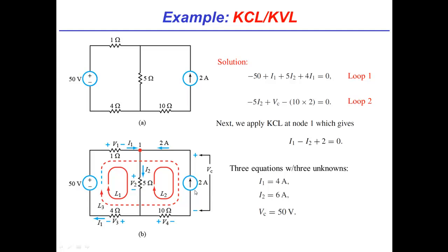We could do some simple tests. I'm not going to go ahead and do them, but I'll point them out to you. You can go back and always check to see if you'd made a math error with some simple tests. For example, you know KCL here better work out. So in other words, 4 coming in, 4 amps, 2 coming in, 2 amps, 4 plus 2 better equal what's coming out the bottom, and that's 6. So that works out. So you can test with self-consistency.